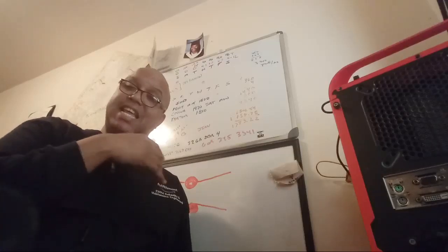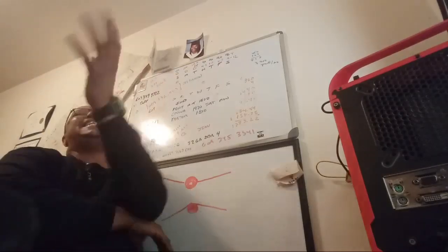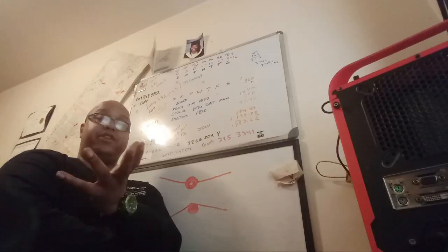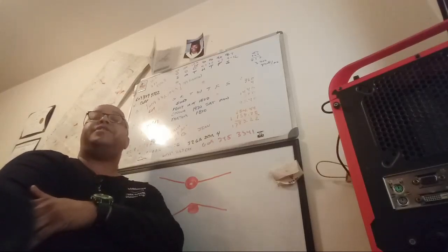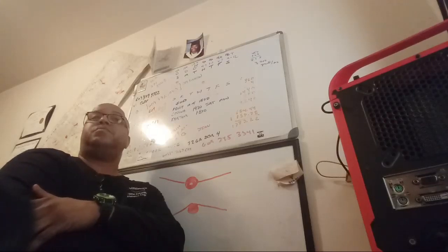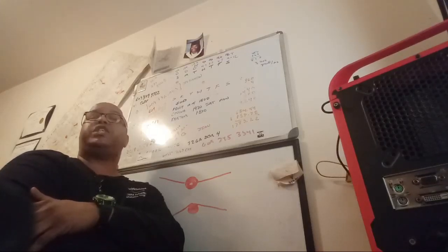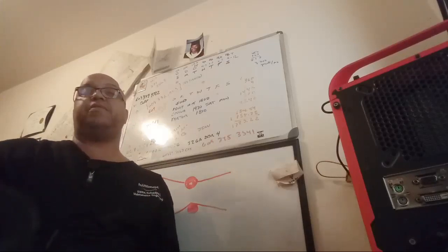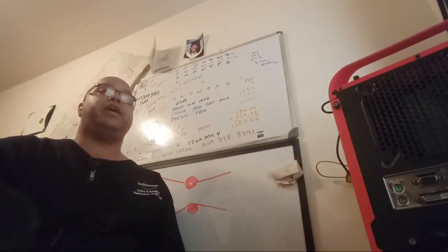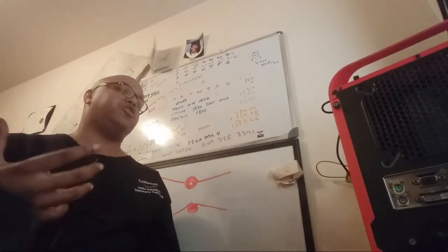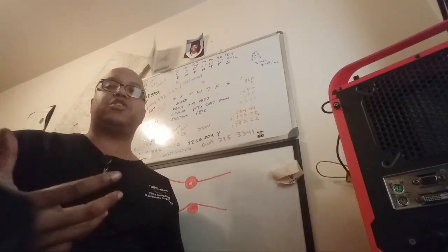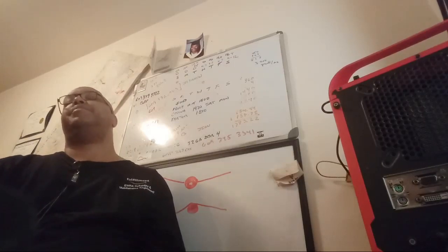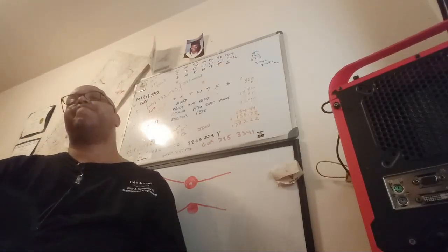No, indicated. Listen to the word indicated. Your indicated altitude or your indicated airspeed is the speed or the altitude you read directly off the instrument with your eyes. If you see, say, 120 on your airspeed indicator, 120 is your indicated airspeed. If you see 5,000 feet on your altimeter, that is your indicated altitude. That is directly what you're reading off the instrument.